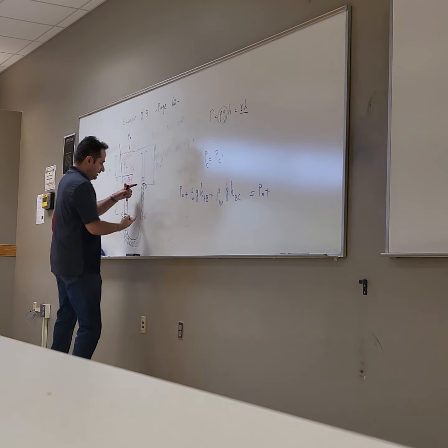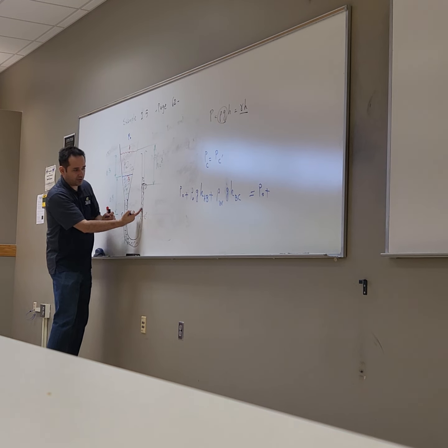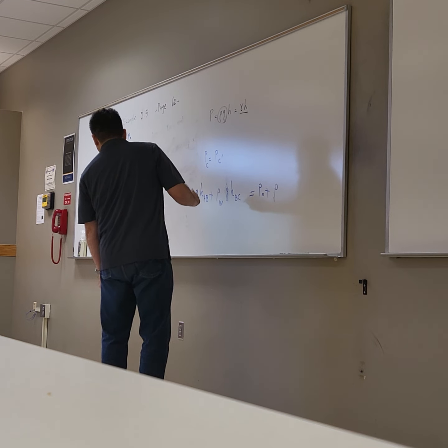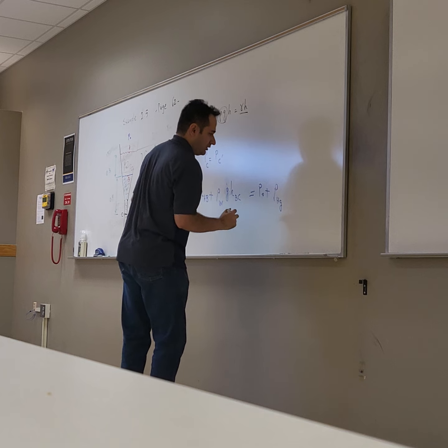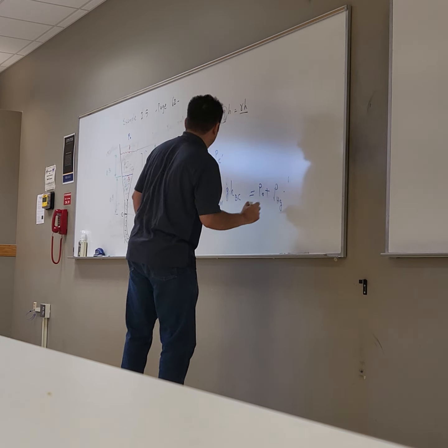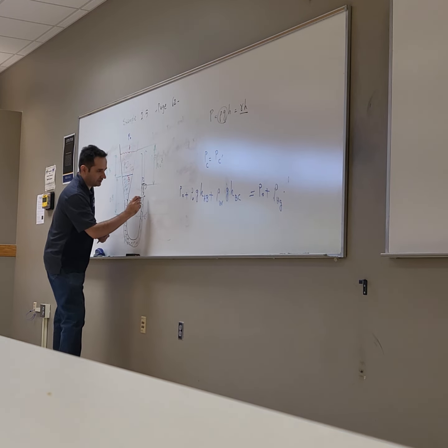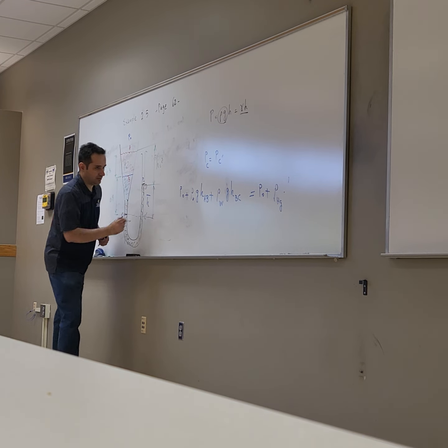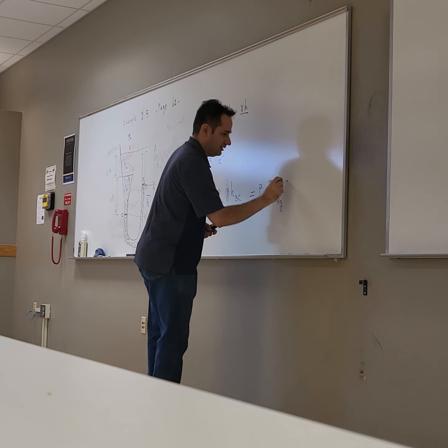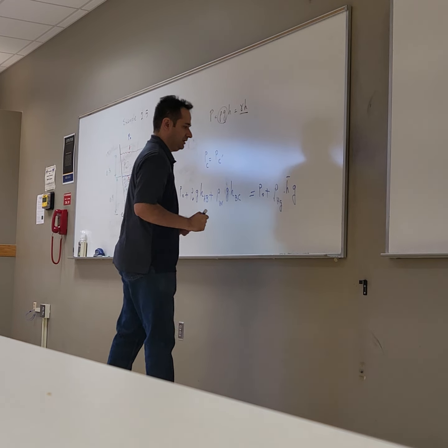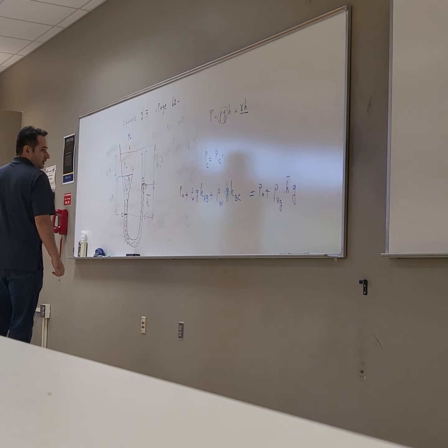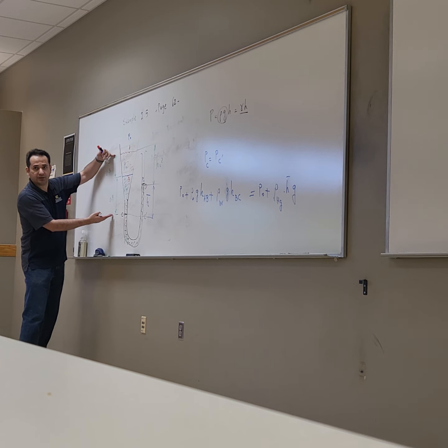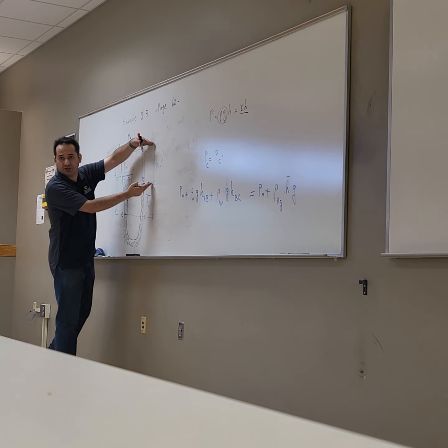plus the pressure that comes from the height of this mercury column, which is the density of mercury, rho Hg, times this height, let's call it H bar, times g. Right? So what is H bar? I can write H bar is equal to this length minus H. You see that from here?